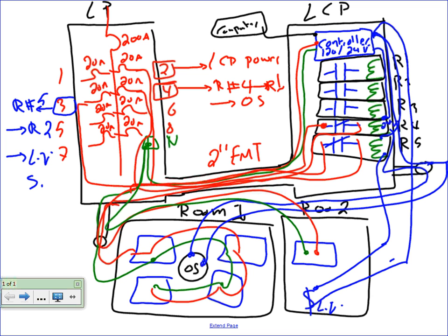So see, it goes bigger than that. So now this is just interface. Now you bring a signal to the controller. Inside the controller, you have the ability, they call it sweep, all the lights at night to save energy. So at night, around 10 o'clock, when everybody's gone home, if somebody forgot to turn the light in their office off, they have a signal, programmed in the control panel. You don't have to use the laptop. You can program the control panel. At 10 o'clock, shut down every single relay in the system.